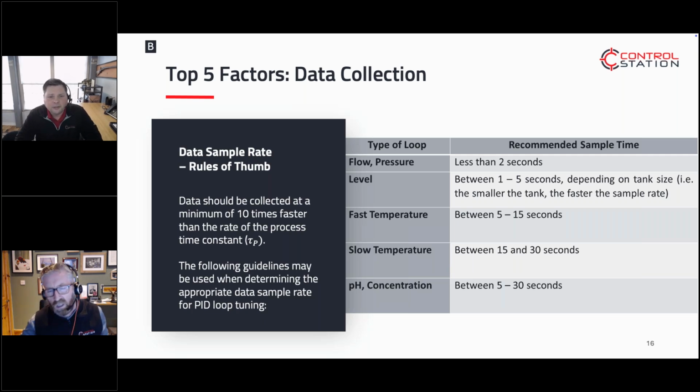Damien, any other thoughts on that? Yeah. From a practicality point of view, sampling doesn't mean you have to have a different sampling rate for every type of system, because in process manufacturing, we don't travel at light speed. The processes are most likely multiples of seconds or minutes in their time constants. So to sample consistently, it's very easy to say all our historians sample at 1 to 2 seconds, or some slow number, which is more than adequate for the majority of systems.